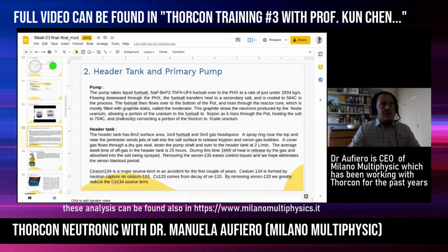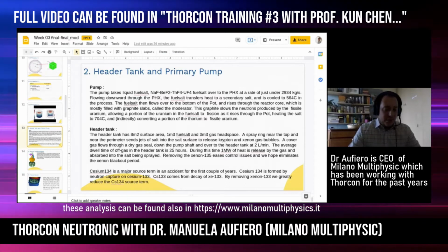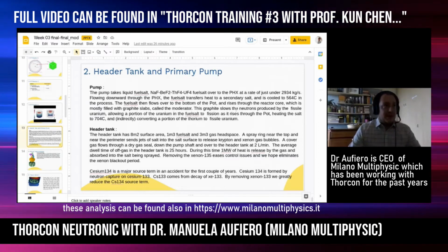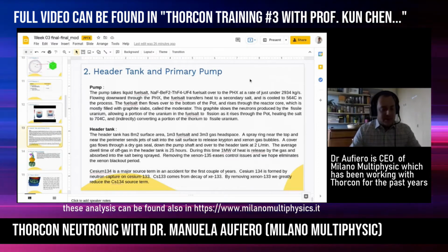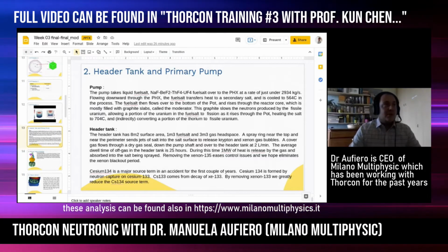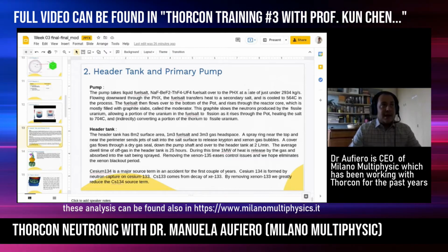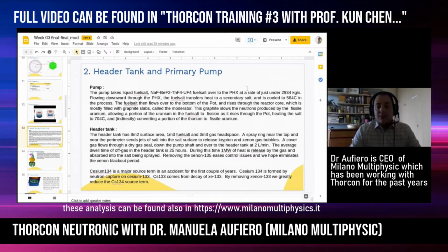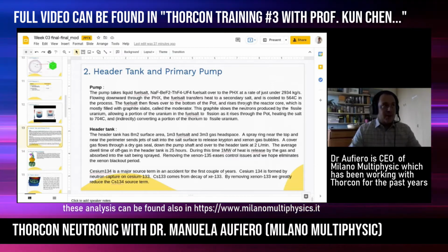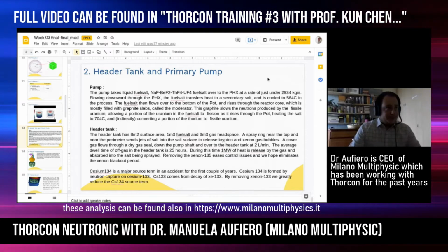The circulation time, again, has changed in the recent design due to a more accurate estimation of the salt capacity, but let's say it is in the order of 10 to 15 seconds recirculation time. That means that we have to move around more or less 1 cubic meter of salt per second. So that dictates the requirement of the pump.